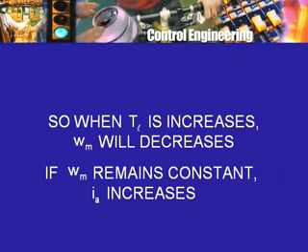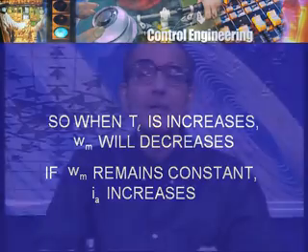Of course, the armature current will not be at the old value. What will happen is the speed will decrease a little bit, and the armature current will have increased from the rated value. So, the drive will no longer run at 1500 rpm. It was designed to run at 1500 rpm under rated conditions, assuming supply voltage was this, torque was this, etc. When the torque is increased, then the speed will be less than 1500 rpm. The armature current would have also increased a little bit.